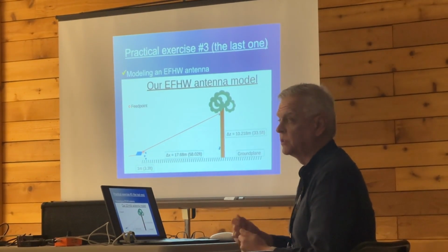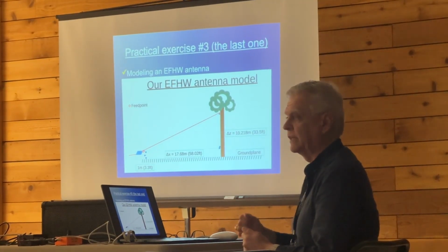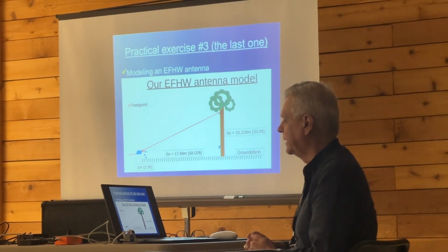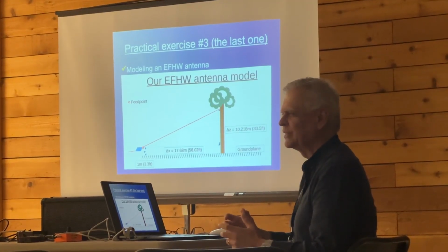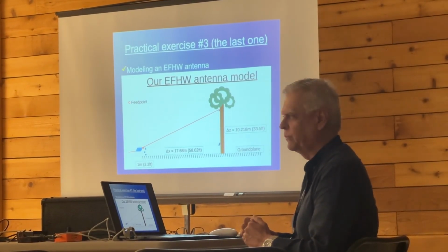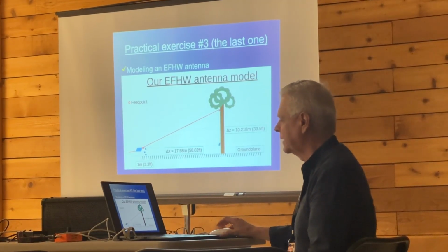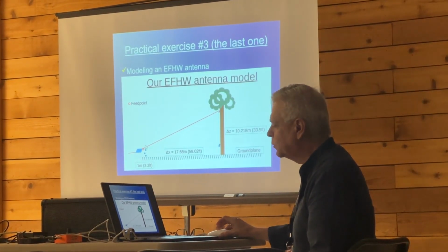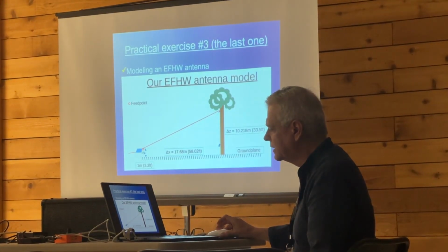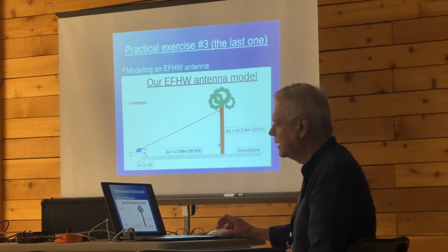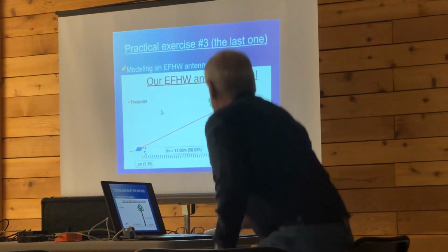The Brazos Valley Amateur Radio Club during field day activities this past year, 2023, had a practical exercise in which we actually built an end-fed half-wave, the 49-to-1 transformer, which is at the core of the end-fed half-wave antenna. That 49-to-1 transformer is right here, is this box right here. This fellow right here. Let me show it to you.